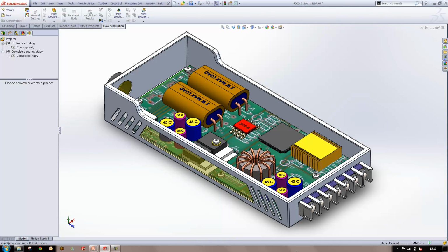So when I say a lid, it's just a solid body which has been used to plug that gap. We're going to apply properties to that gap or to that solid body or lid in a moment. We've done something similar over here to account for the fan, and we've also got some lids on these slots. You just can't see them, or for some reason I haven't made them yellow.